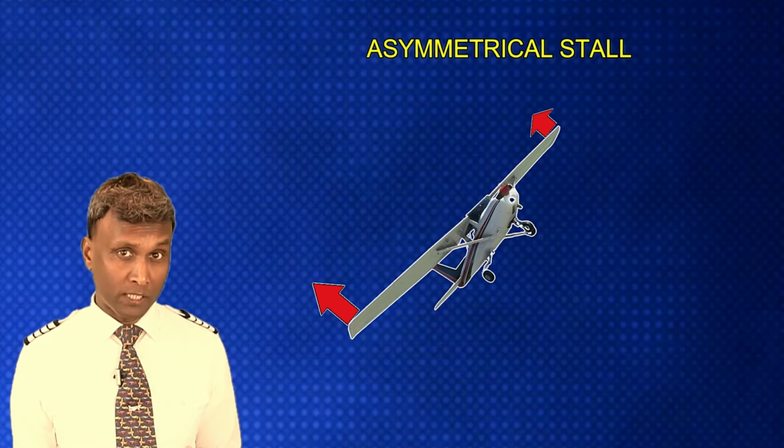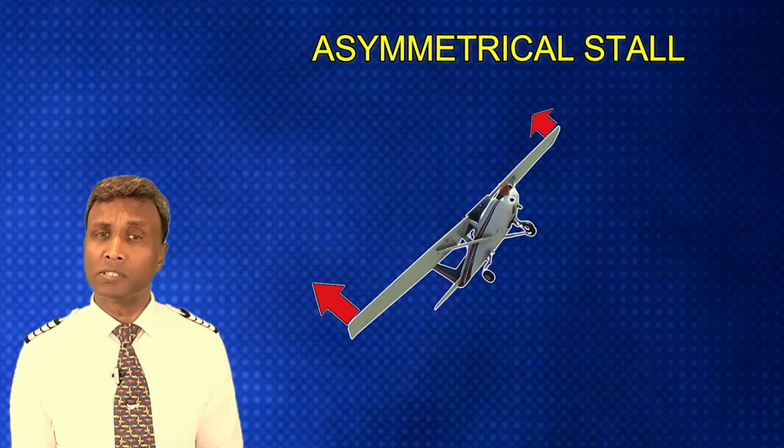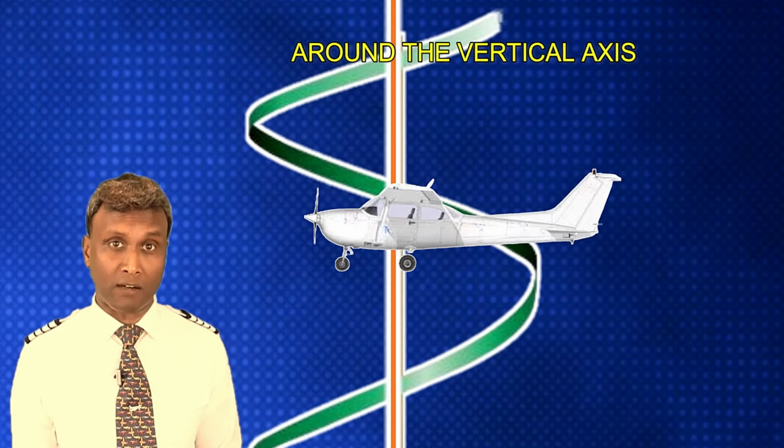Spotting a spin is quite distinctive. The aircraft starts spiraling and the nose points downward. During a spin, auto-rotation occurs due to an uneven distribution of lift across the wings. This imbalance in lift, often caused by factors such as asymmetrical stall conditions or control inputs, results in a rotating motion around the vertical axis of the aircraft.